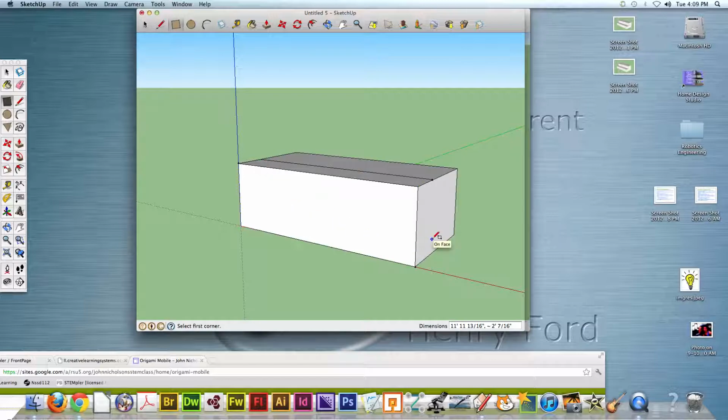That whole section where I made that rectangle, now we want to push downward so that it's 2 feet off the ground. So once again, pull out your tape measure so you can see where to stop. And let's make it 2 feet off the ground. Oop, I don't know what just happened. I'm going to press Command Z. I'll just stop it there right now. Let's just make it 2 feet off the ground. Okay, so we're going to push it down to this black point right here, that little black dot.